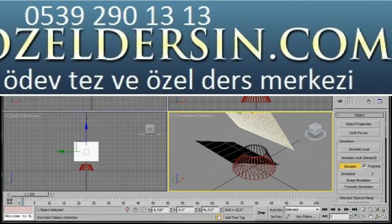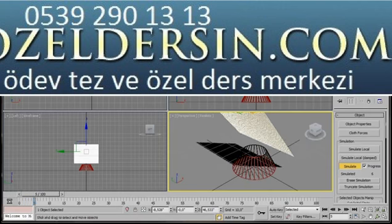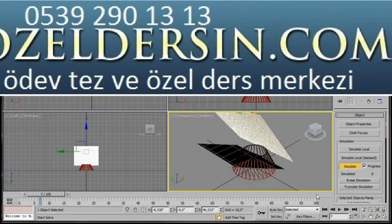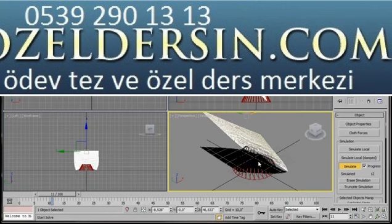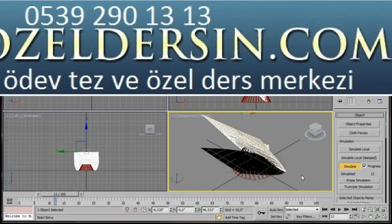Here we are. Now the cloth dialog has appeared. Here we can control the progress. We can see the elapsed time, the last frame. Actually what we are doing is creating 100 frames. If you look down here on the timeline, you can see how the slider is moving along. But we're only interested in the last frame. If we look now in the front viewport, we can see how the plane is starting to fold and bend over the collision object. I'm going to turn the video off and I'll be back when it's finished.